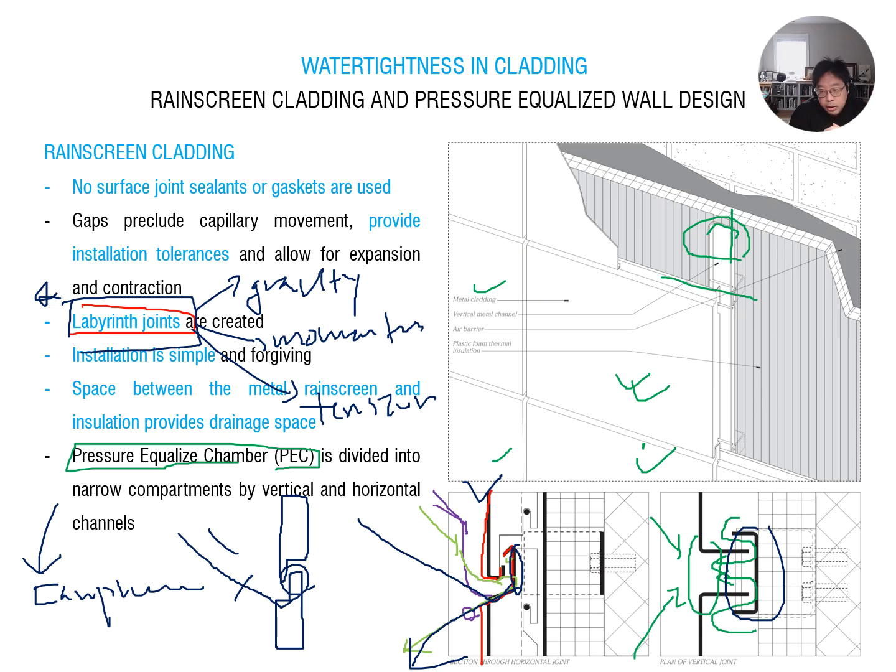without this consideration, the water keeps being delivered from outside to inside. It means your assemblage keeps being wet. So even if it keeps ventilating the air, sometimes it is a little more dry, sometimes humid.